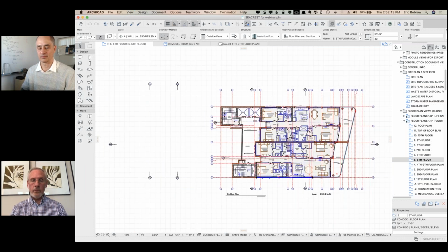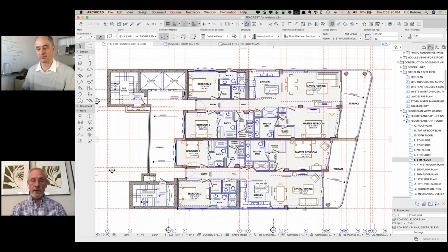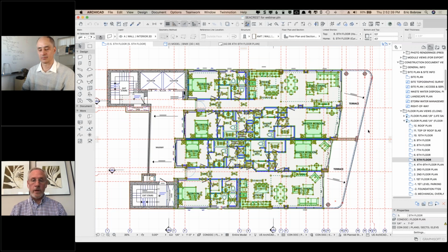Most of the loading comes back to the back end of the building because there's mostly windows at the front and the sides. We have one shear wall right behind the kitchen that gives us a little bit of stability there, but the rest of all the loading is carried back to the stair and elevator towers. So those walls, some of them are fairly thick and concrete. The walls that are in between the columns along the side are actually not structural. They're infill walls.